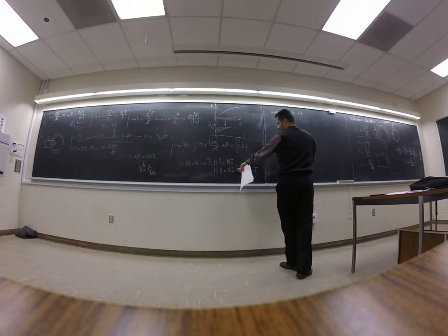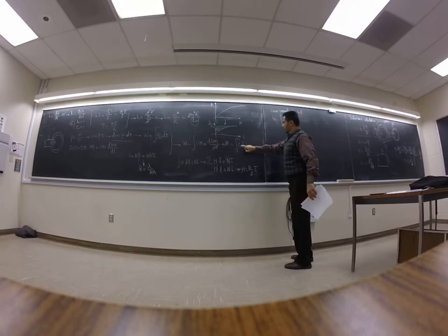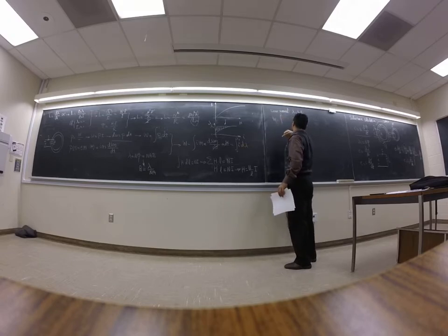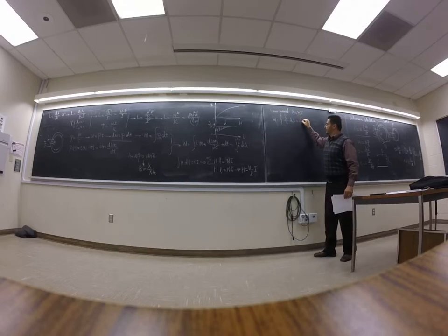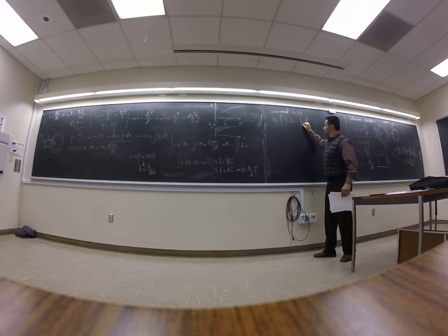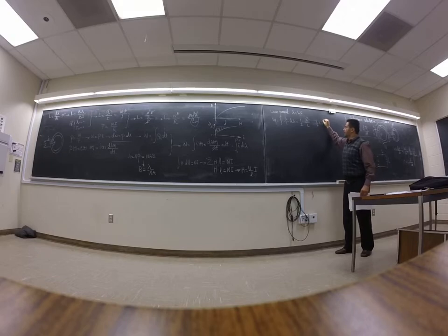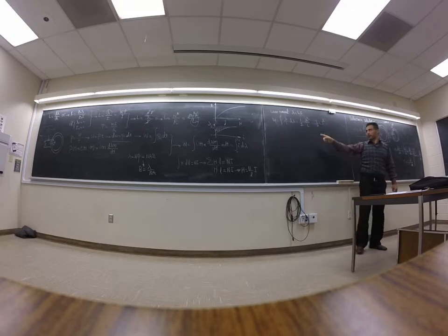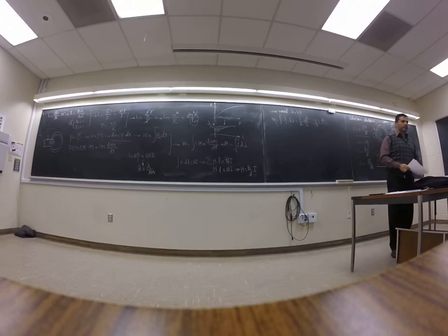Now, come back here. W is going to be the integral of, I'm going to replace I with lambda over L, d lambda. How much is this one? Lambda over L, or I can say one half L i squared, right? Just replace lambda with this one. So this is the energy stored in the inductor.